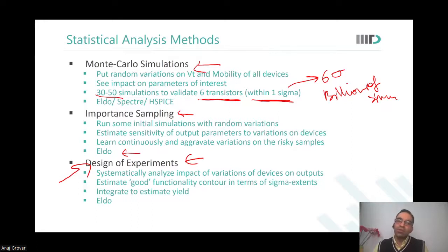So it is kind of you doing some kind of machine learning while running the simulation and then choosing samples such that the probability of their failure is higher. Okay, so now to qualify 6 sigma, you do not need to run billions of simulations. Possibly 10,000 simulations will help you arrive at the worst case cell, because you're gravitating towards the worst place where the failure could happen. Is that okay? Yes, sir.